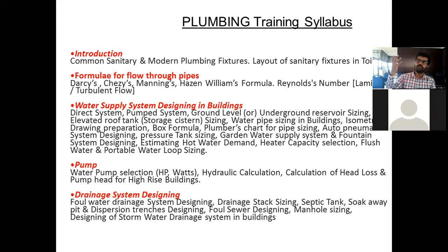Okay. There are different methods to give pipe connections to the individual fixtures or toilets. You can have a loop connection. You can give a loop, a round connection from the overhead tank. From there, you can take individual branches from the top itself. Okay. That is mainly better if it's a flat or an apartment.